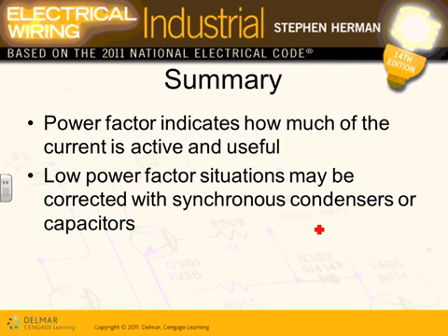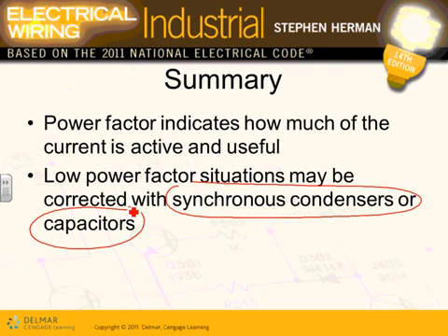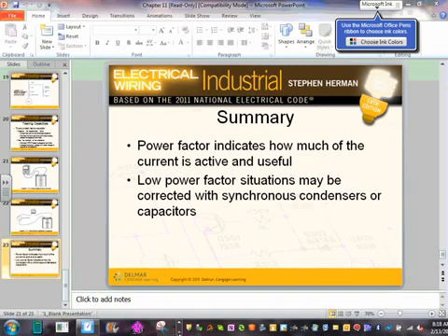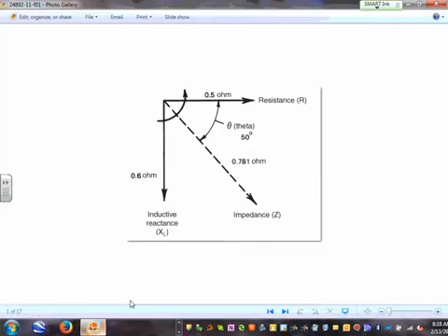Correcting power factor to improve, adding capacitors to inductive loads, and adding a synchronous motor to correct the power factor. So I can't get you guys to more than understand that synchronous motors and capacitors will correct the power factor. We correct power factor typically to 90% or higher, not to 100%. Typically we don't do 100%. Okay, there's a couple of tables, guys, I'm going to be using in a second here. So I would like you guys please to look at them and see how you can use them. We talked about the angle, guys, the power factor.